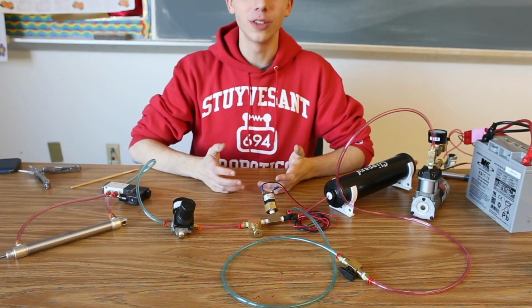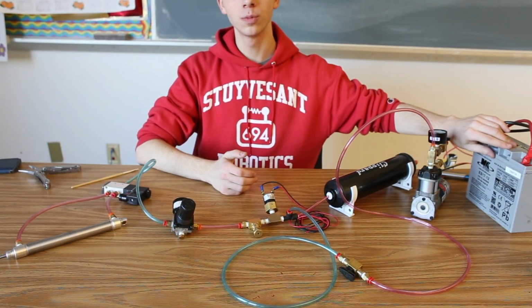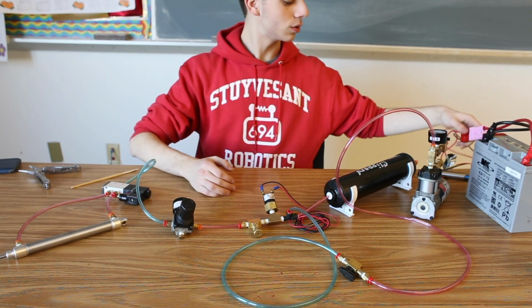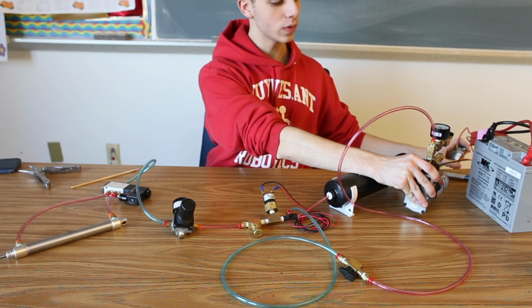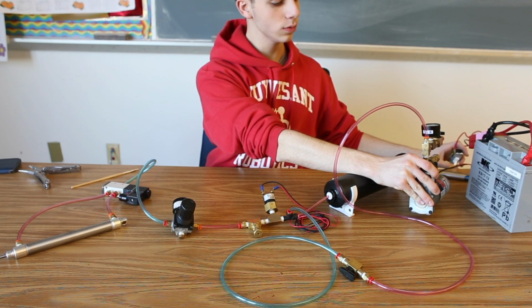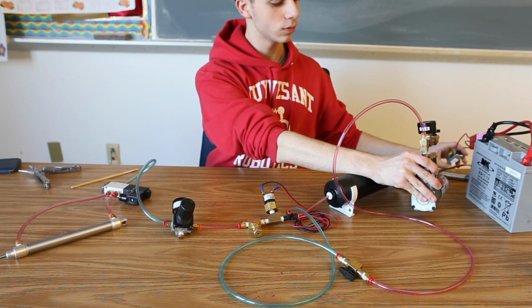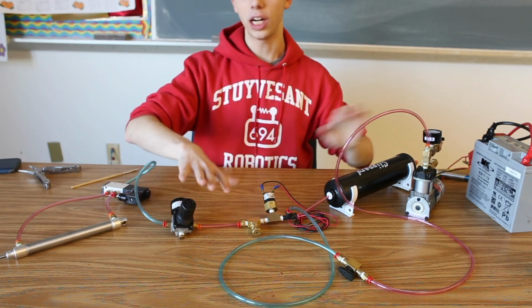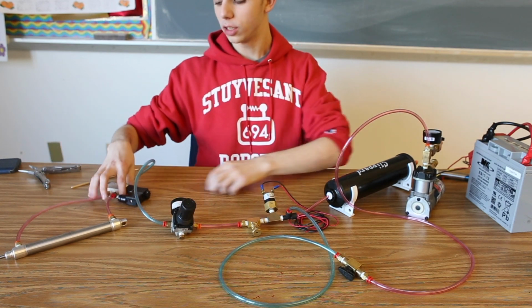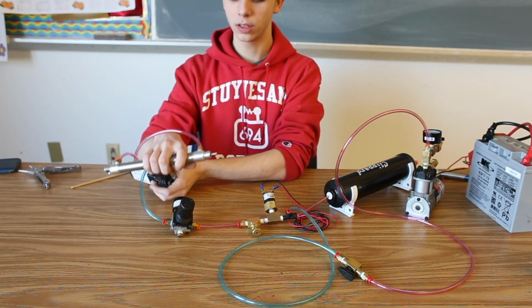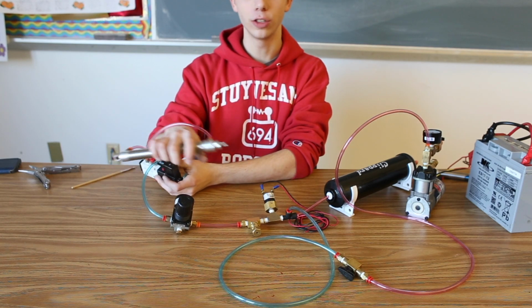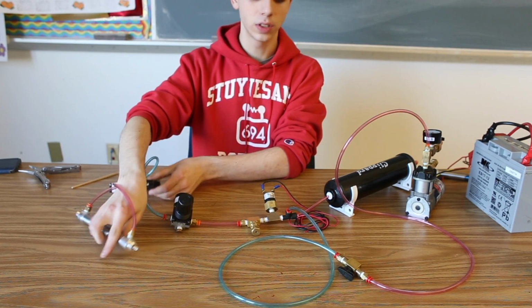For the purpose of this video, I'll be compressing directly from a battery. At competition, it should be your robot controlling the compressor. So, turn it on. Right now, the air in this side system is 80 psi, and after the regulator, it's 60 psi. I can manually actuate the piston. And on your robot, it'll be your robot electronically actuating the piston.